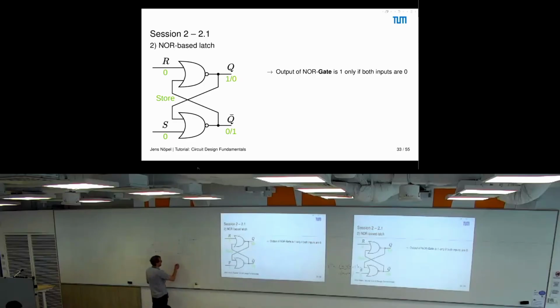And if we have a look at the logic table of a NOR, let's call the inputs A and B. As long as you have a 1 in it, the output should be 0. And if there's no 1, the output is 1, right? And now the interesting thing here is, as long as A is 0, you see that you have an inverter.